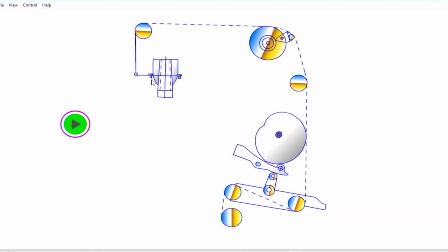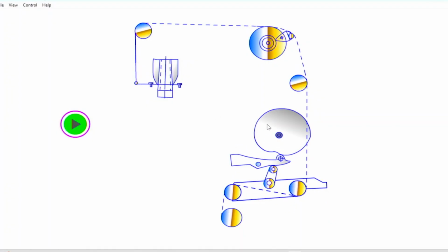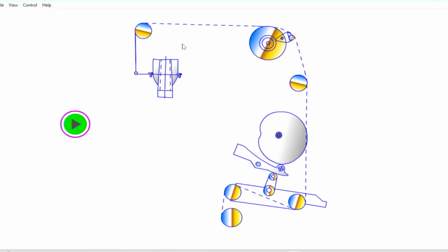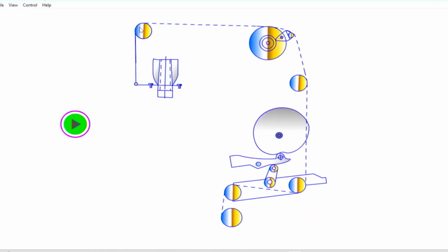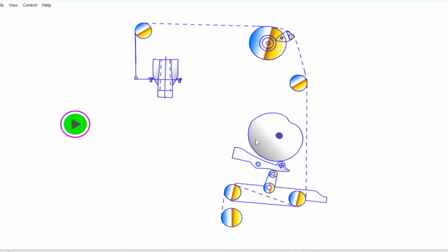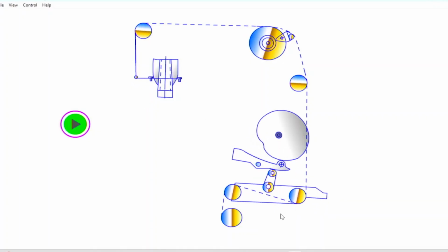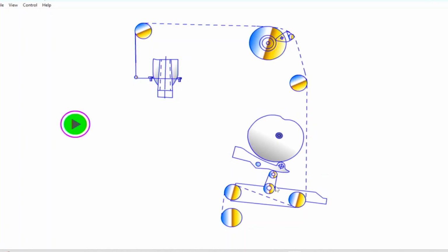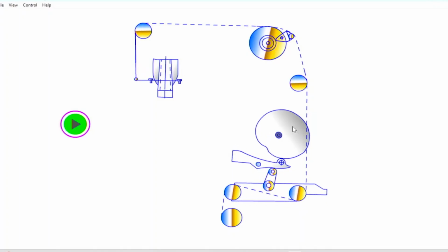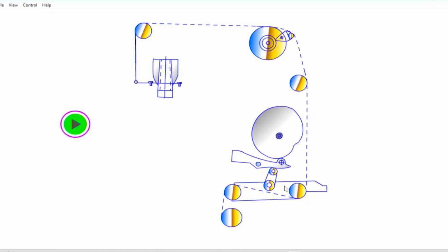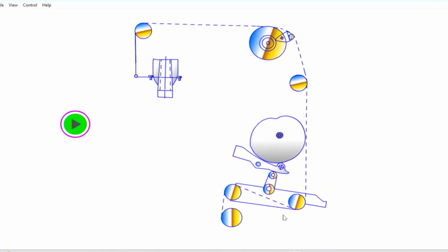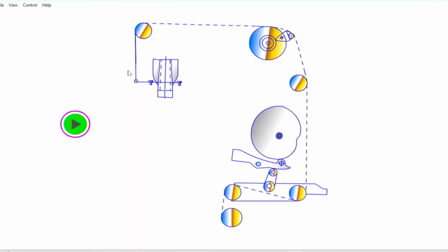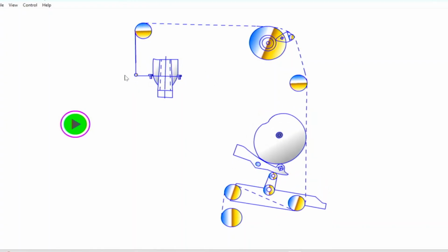is changing. The ring rail is basically hanging on this rope, and the lever is pushed against this cam profile, and the cam profile only presses downward. The upward movement of the lever is done by the mass of the ring rail, which is a heavy ring rail hanging,